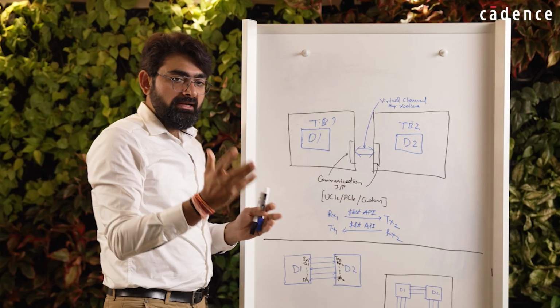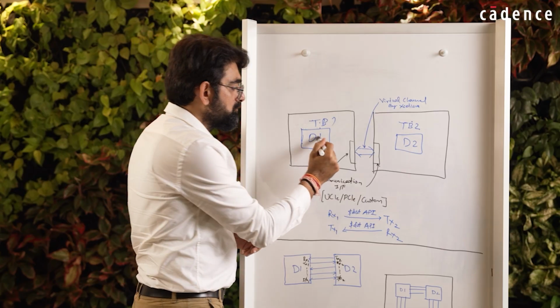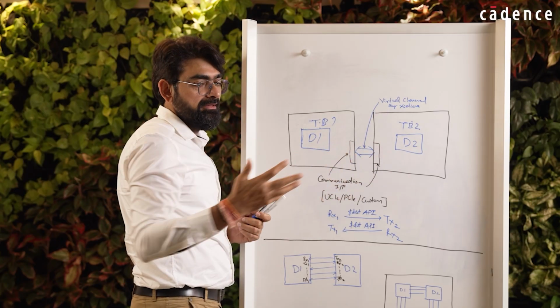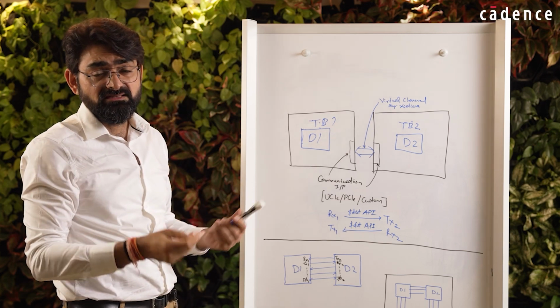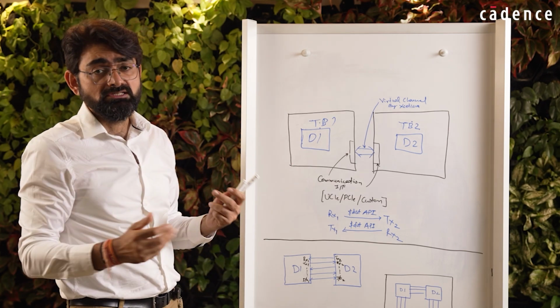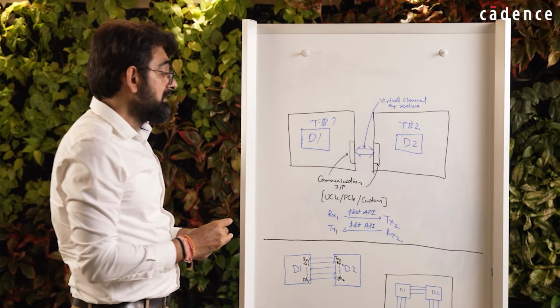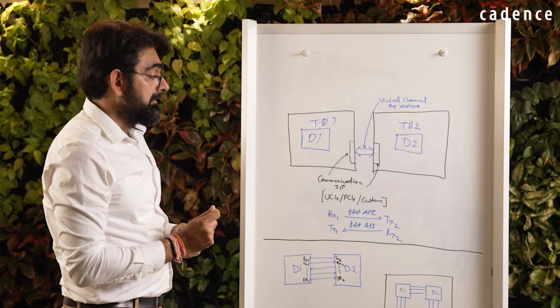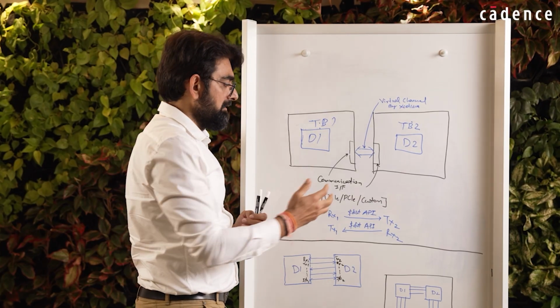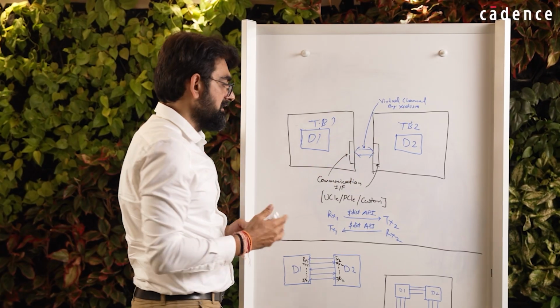The tool very easily connects the two dies together via the communication interface. It could be, as we know, for multi-die designs, a UCIe. In some cases, for heterogeneous ones, a PCIe interface works as well. Or there could be some custom high-speed interfaces enabling the die-to-die communication in your design.